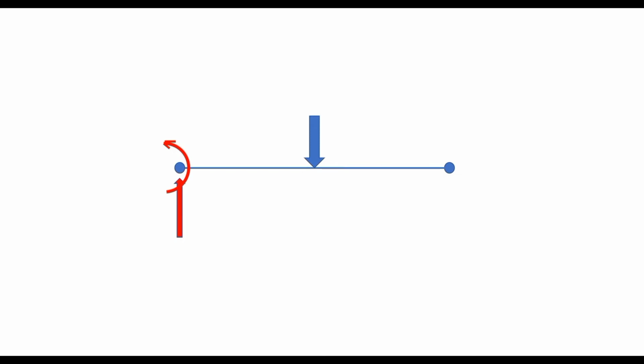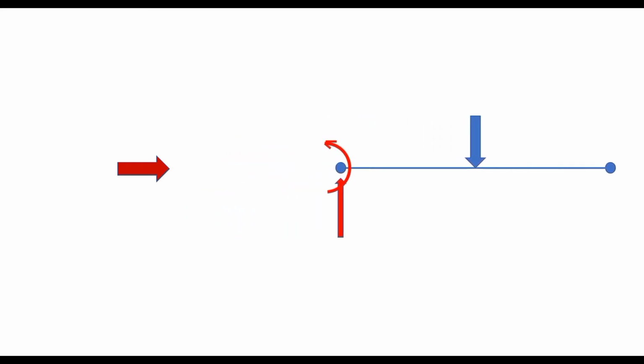Now, we see that for the current loading criteria, this arrangement has lent stability to the beam. But is this system stable against any general coplanar load system? Well, the answer again is no, because if we have a horizontal load applied on the beam, it would again, as before, translate in the direction of the applied force.